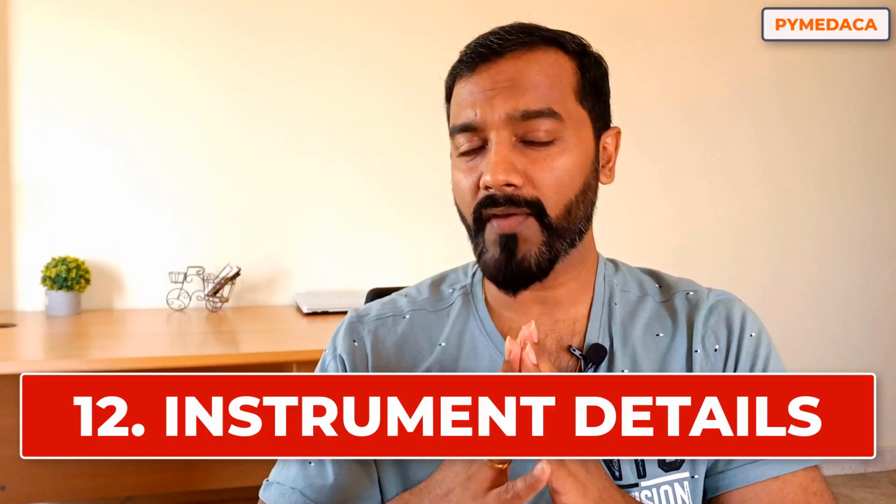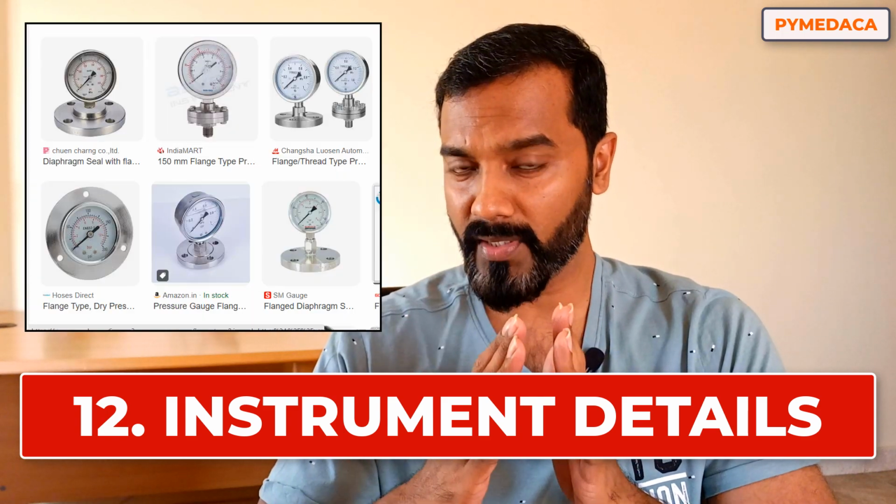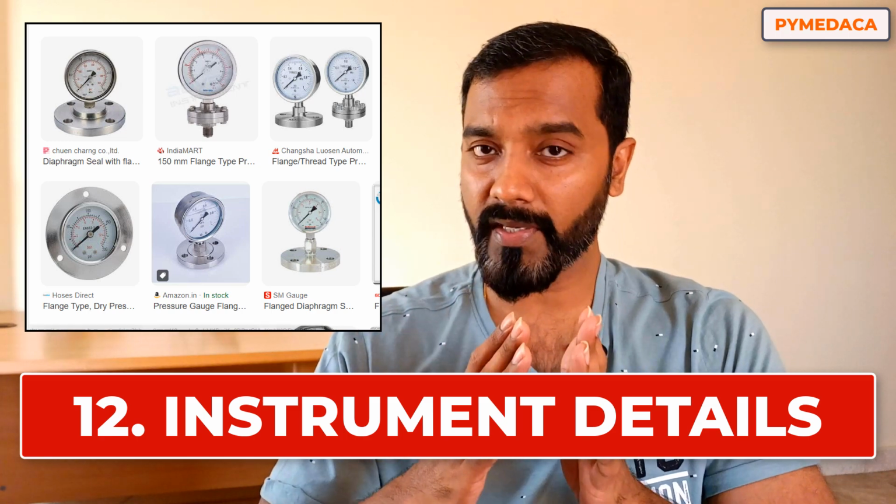The next detail you should have is instrument details. What are instrument details? What is the type of instrument, whether it is a pressure gauge, temperature transmitter or level indicator, what is the end connection, and what is the overall dimension of this instrument, whether it can be suited in your existing layout or not. All these things you need to verify. For that, you need to have the dimensional requirements and the end connections.